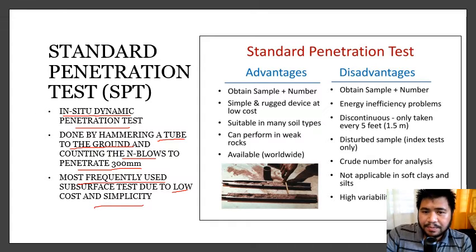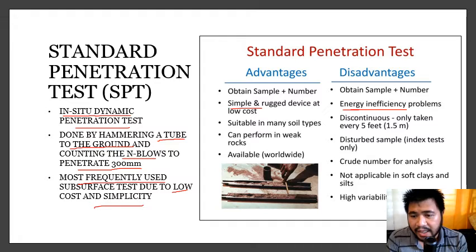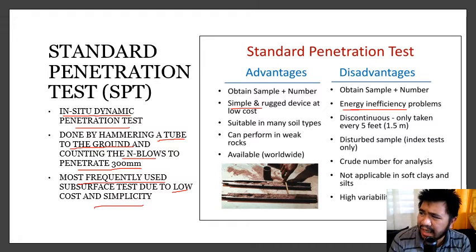Right? So advantage, it is simple. Disadvantage, you have energy efficiency problems, meaning it's actually quite hard to get consistent SPT readings, especially if you're doing the manual version of it. In the manual version, basically the hammer is being dropped by your operators.